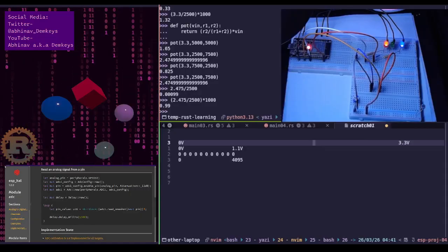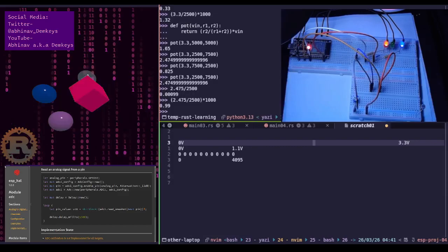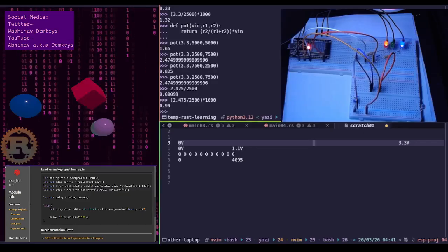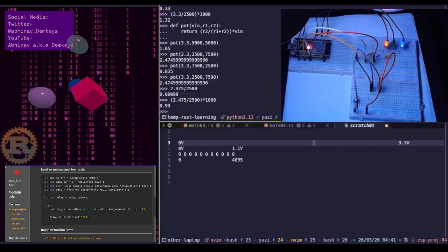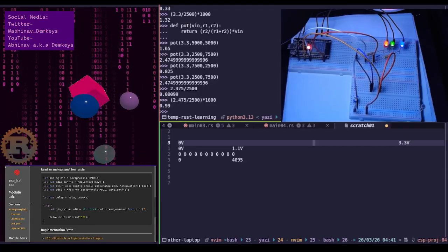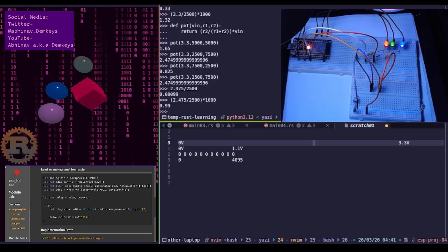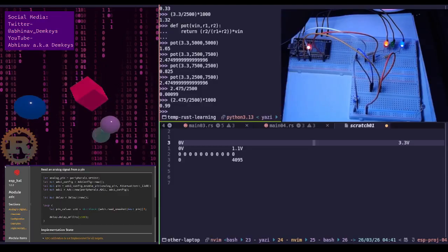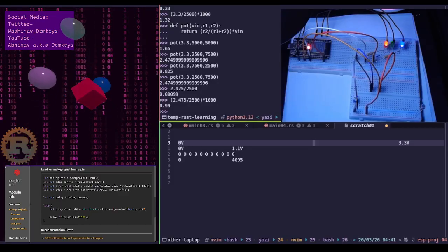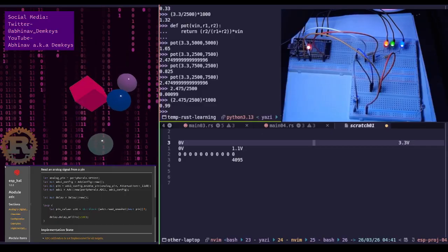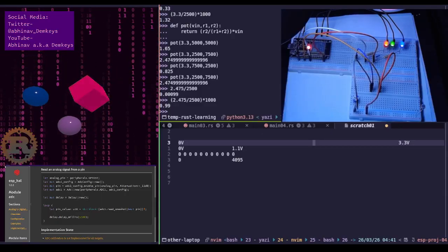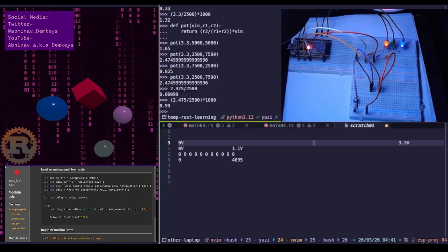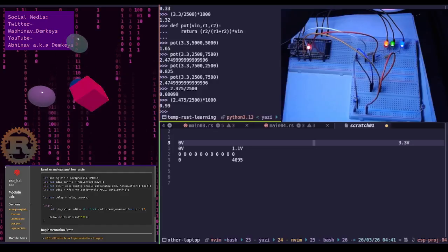Okay, so the maximum safe voltage. In that case, if VDD is 3.3 volts, then the max safe voltage here is 3.6 volts. Since your potentiometer's high side is connected to 3.3 volts, the wiper, which is the middle pin, can only output between 0 volts and 3.3 volts. You are well within the safe zone. If you were powering the pot with 5 volts, you would definitely need a voltage divider to protect the ESP32, as 5 volts would likely damage the silicon.